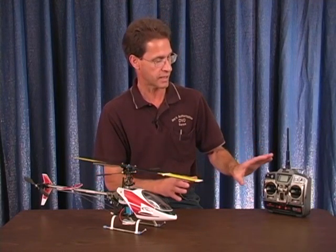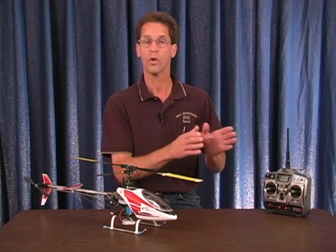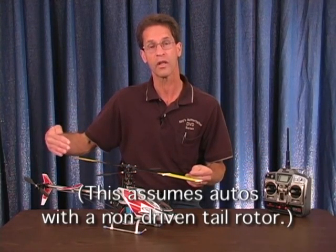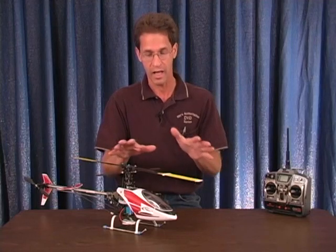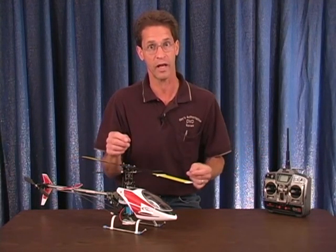Because the DX6 does not have dedicated trims for throttle hold, when we enter an auto rotation, the tail rotor is going to hold the hover pitch setting. And again, you can look at the DX7 and you'll be able to see how we set up the DX7. I'm not actually going to fly the DX6, so this is why I want to give you that warning.